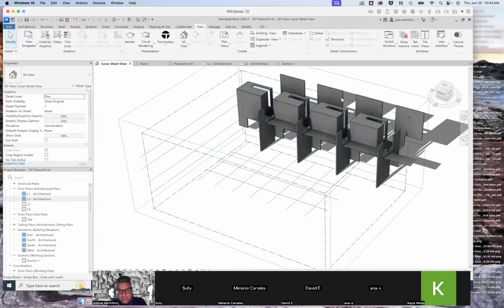What I would do is I'd look at this and say, okay, modularity and repetition, I have 1, 2, 3, 4 modules. I have sort of A, B, right? A module and then a space, a module, module, space, open space, module, open space. So A, B, A, B, A, B, A, B. And on the B and the other parts with more depth, I have these vertical planes that can act as light scoops to take south light and bounce it down into the northern parts of the building, where it's getting deeper and further away from the south face, right?